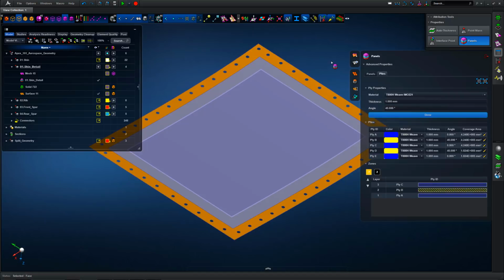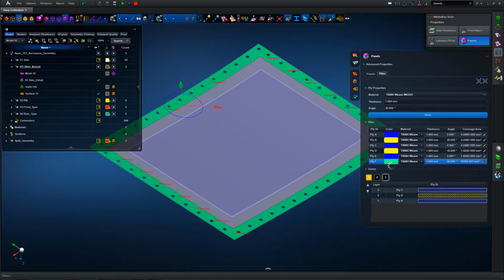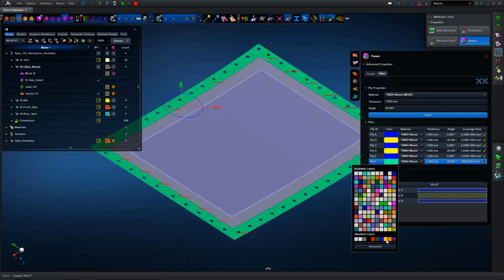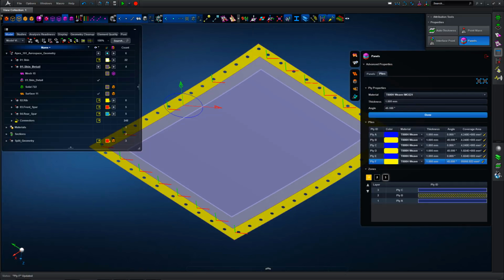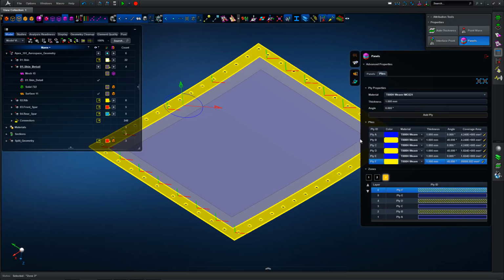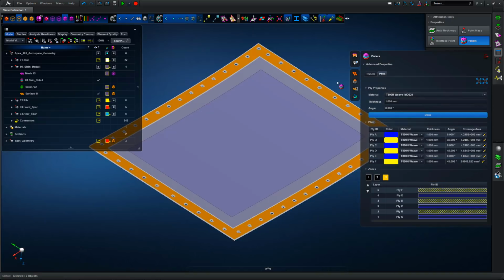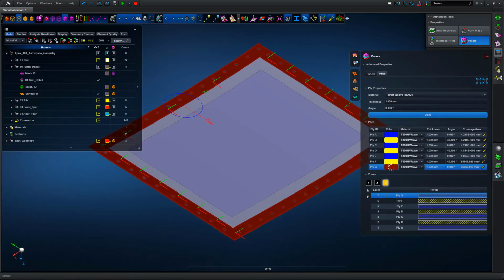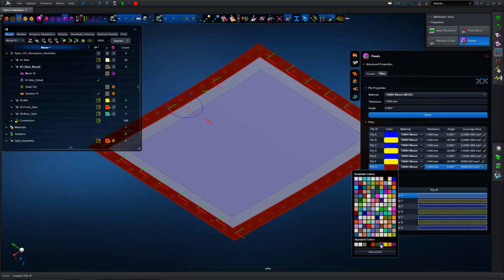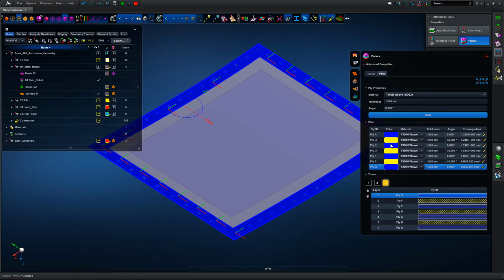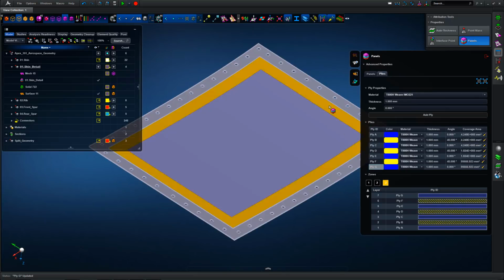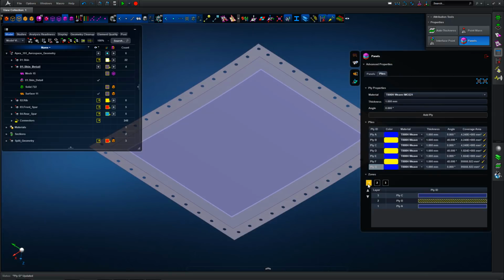And then we just work through to reflect what we were provided in the ply layup definition, and we can see we now have a number of zones generated based on the plies as we create them. So again, very straightforward, and we're not picking FE entities or anything like that at this stage. Simply selecting the geometry. The generative nature of Apex means that these ply definitions are washed through to the underlying mesh definition, but we don't need to worry about that at this level.